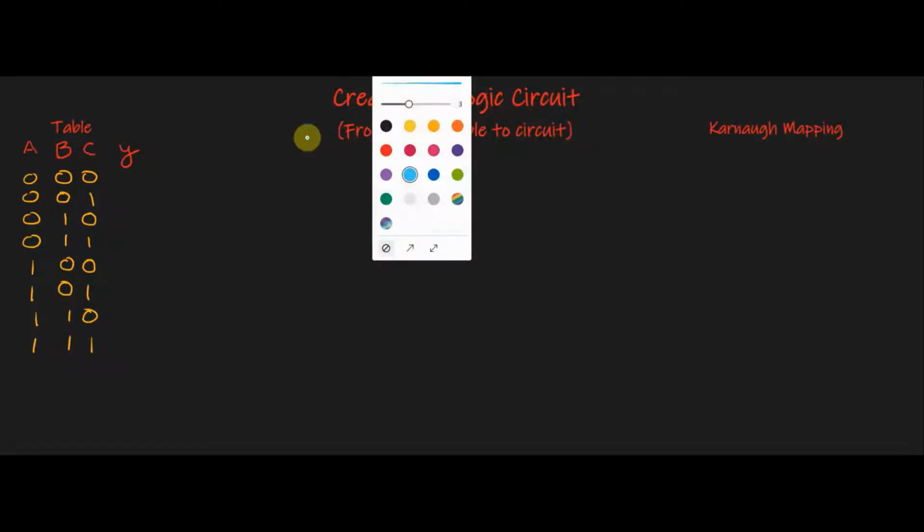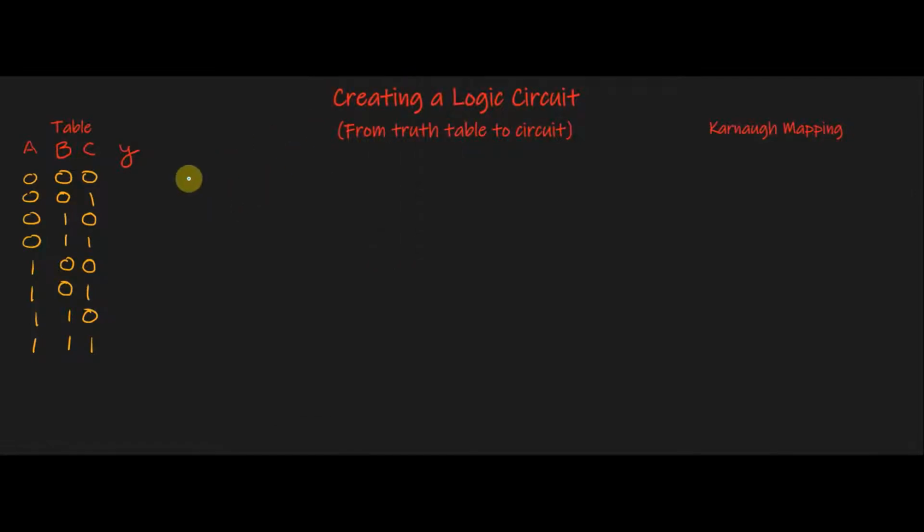So for the sake of this lesson, I'm going to pick this as an output that I want to be 1. This sequence I want is a 1, and this sequence I want is a 1. Everything else is going to be a 0, which means when any of these 3 are true, I want to turn on my circuit. So here's how we're going to do that.